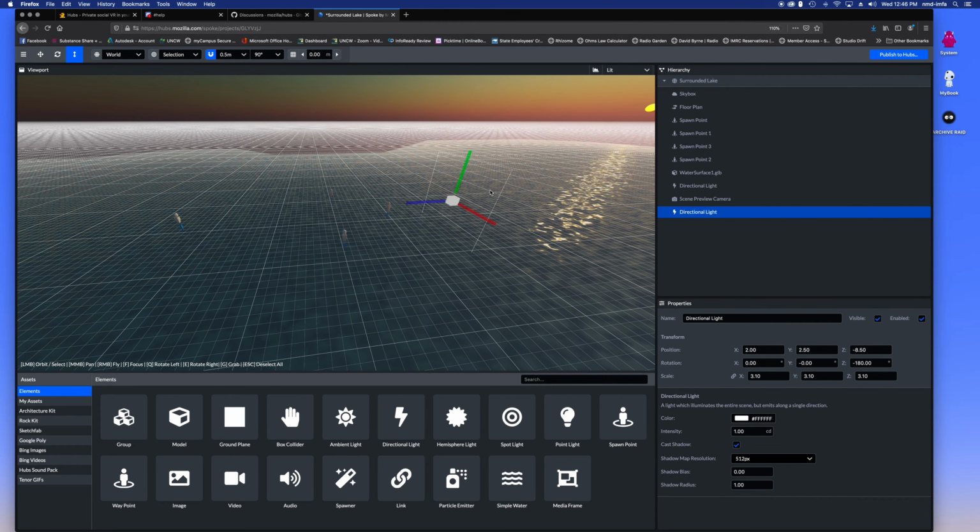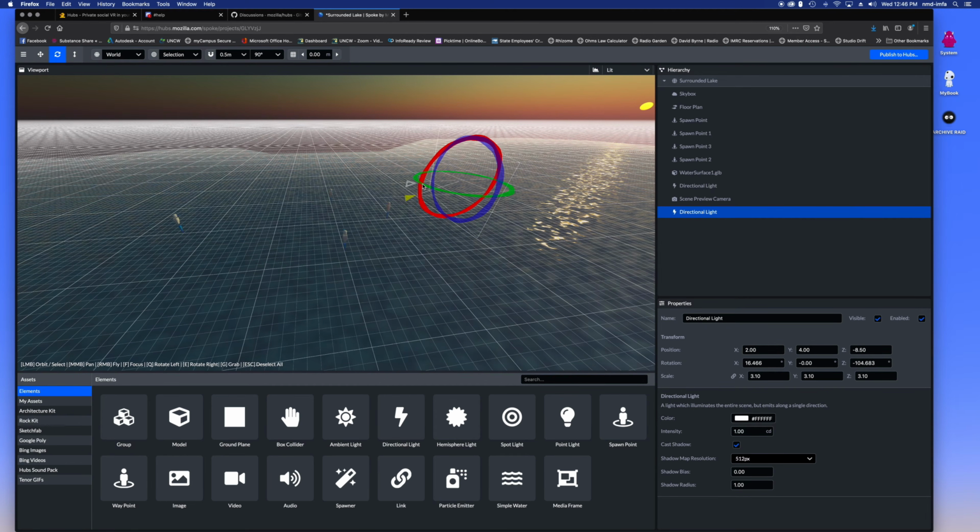I'm doing incremental rotations right there because I have snap turned on up here at the top, so I can turn that off and then I can rotate at a much smaller amount. There we go, and get the direction that I'm looking for. You can see how it's lighting up the ground versus the sky as I rotate that downward. Snap is really convenient because it snaps to the grid, and you can do little increments here, 1 meter, quarter meter, 0.1 meters, all the way up to 4 meter snaps. You can also do snaps on rotation, 45, 30. I use snapping a lot, but it's on by default, so sometimes that's a little bit annoying.